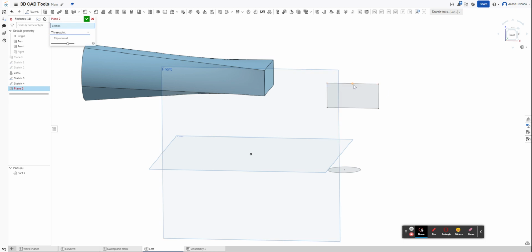And I don't know if it's going to let me use midpoints. Yep, without. I thought maybe I have to go into the sketch region and use the point tool to make the midpoints, but I don't. So I think I'm going to have a vertical plane that goes through the center of the circle and also right through the center of the rectangle.